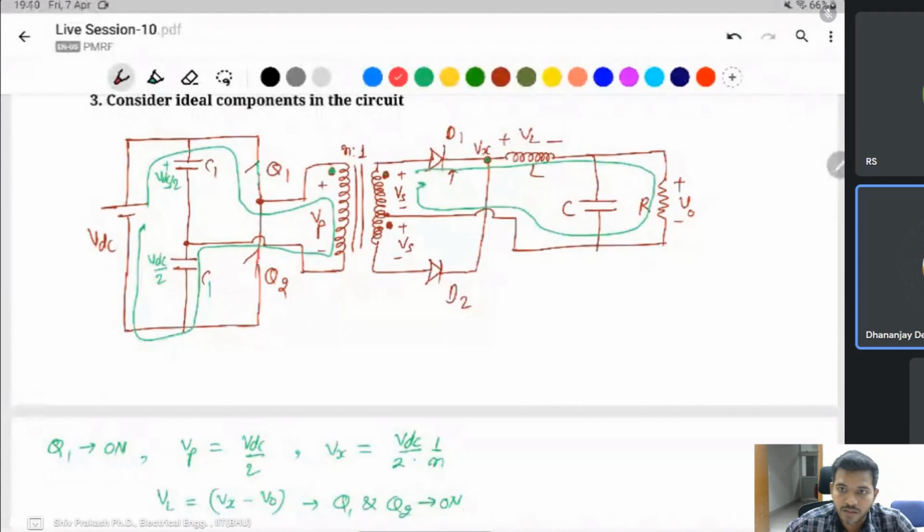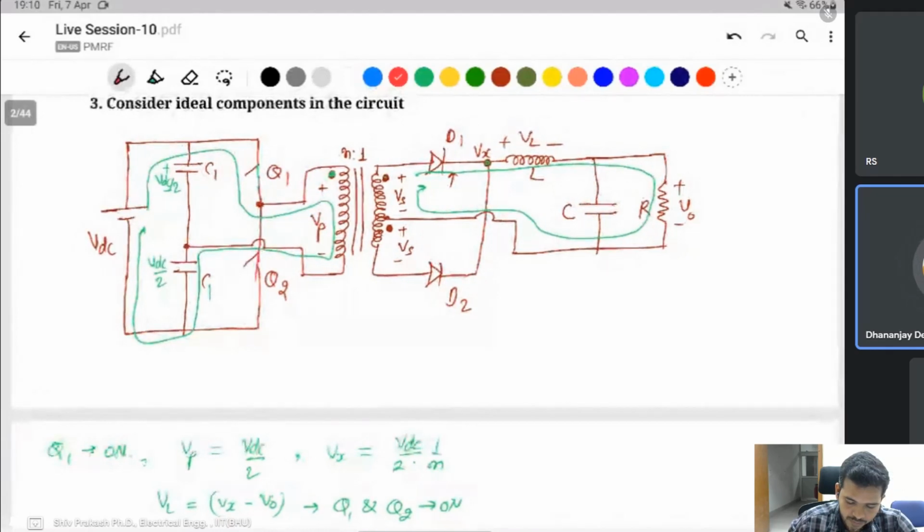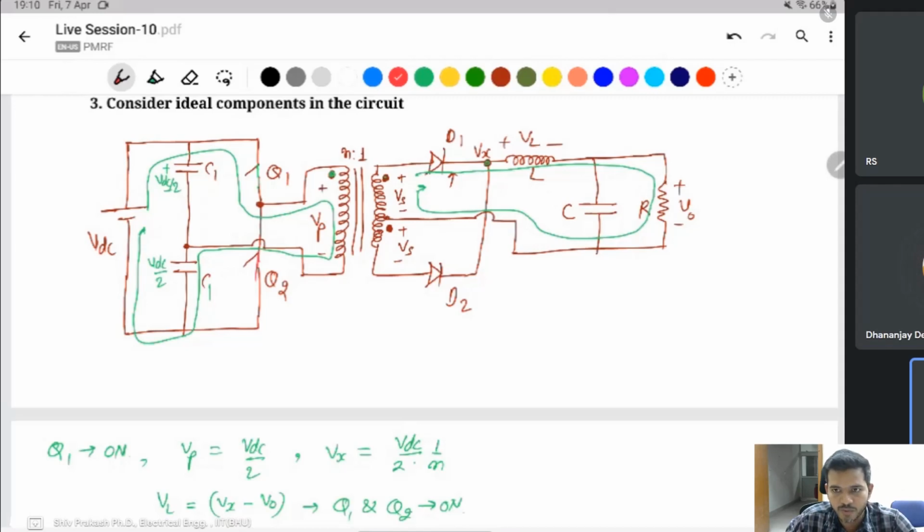We have to have voltage sharing through resistance also, across C1 and C2? No, they are not resistors, these are only capacitors. If two capacitors are connected in series, resistors are not needed to equalize.